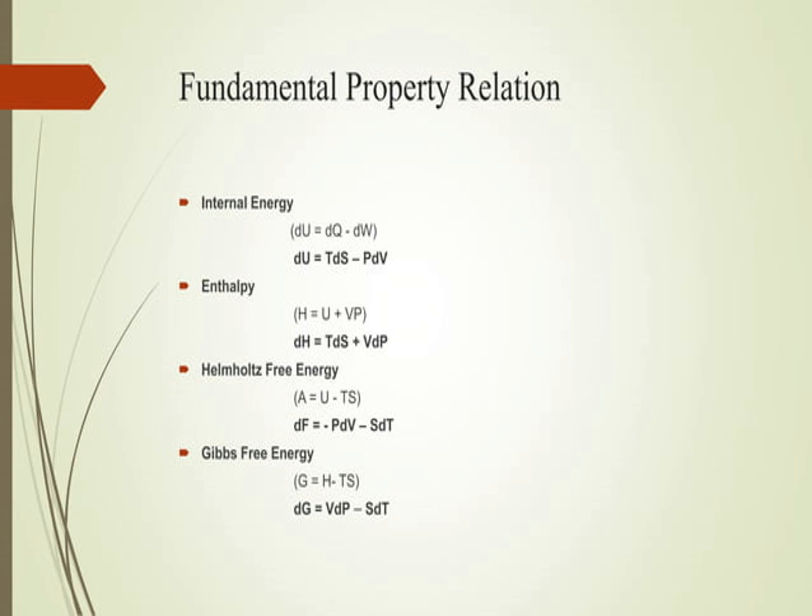So these are developed below for systems of constant mass and composition in which the only external force is pressure and the process occurring is reversible. We already know the first law of thermodynamics for a non-flow process, that is dU is equal to dQ minus dW, right? So we are going to derive by using that first law for a non-flow process.